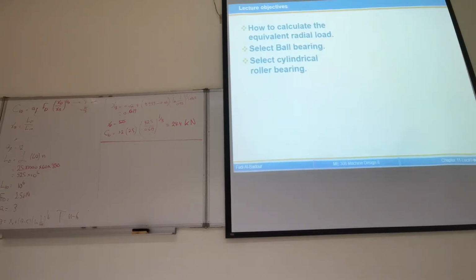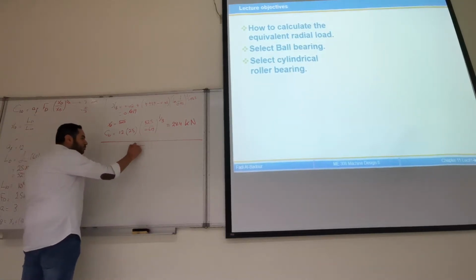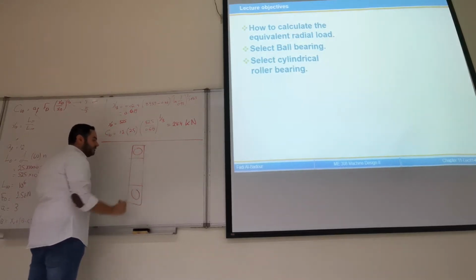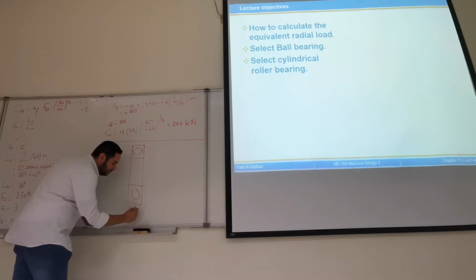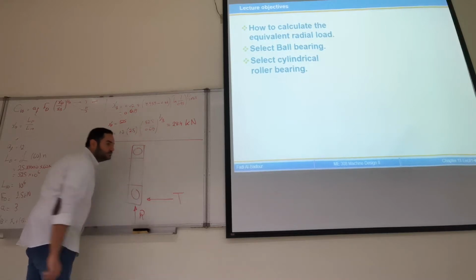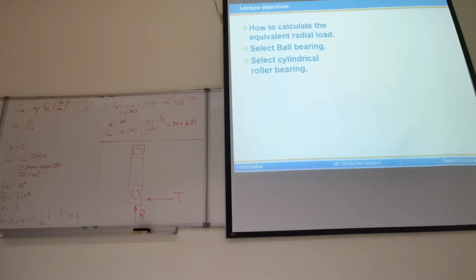Okay. The second part of the lecture continues with ball bearings, but now we would like to look into a different aspect. We said ball bearings have the capability to carry combined load, radial and thrust. Now, the catalog ratings are based on pure radial load.